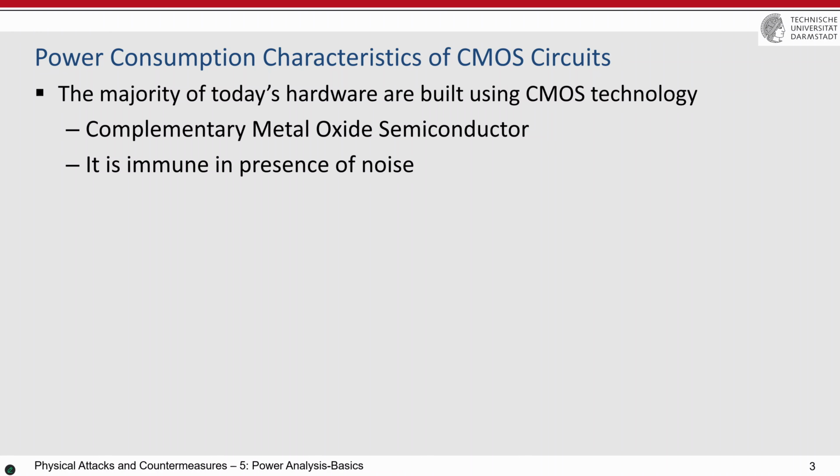Then it means that if you build a circuit with a lot of gates, still, if noise is coming to the system and the output is not exactly 0 volt, for example it's 0.3 volt, it is still considered 0 and the circuit works correctly. Or if the level of the voltage should be 1.2 volt, but it's not 1.2, it's around 1 volt, it means that you have a lot of noise in your system, but still it's considered as logical value 1, and the system works correctly.